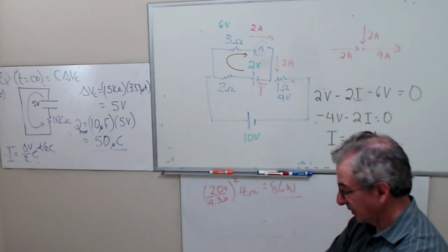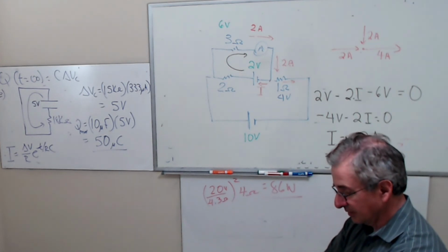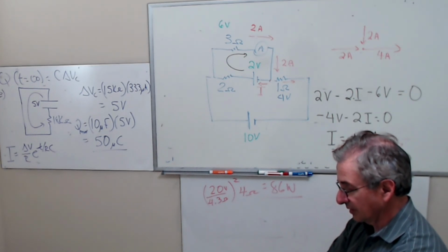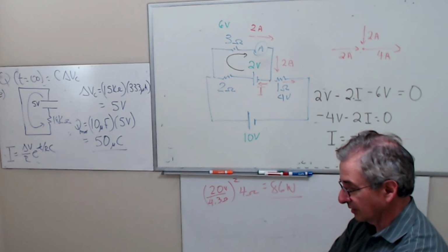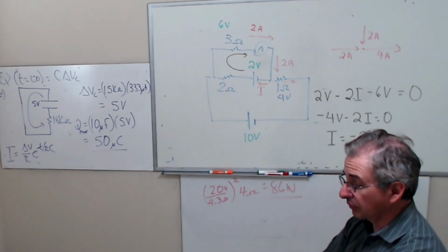Okay, cool. So with the light bulb again, I get why you use the P equals V squared over R formula, but since the voltage for the light bulbs is predetermined and the watts are known, then using P equals VI, we can find that they have different currents, right? But that's the current that's required to light the bulb up, to make it run at that power rating.